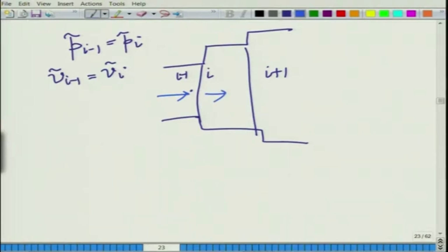So, we are considering the notional discontinuities just as if they were a regular discontinuity. The regular relations that would be valid for a sudden discontinuity, what we were analyzing so far, also hold for this one. So, pressure across this interface between duct I minus 1 and I is the same, as a planar wave front propagates, and the mass velocity, or volume velocity, of the fundamental mode is also the same.